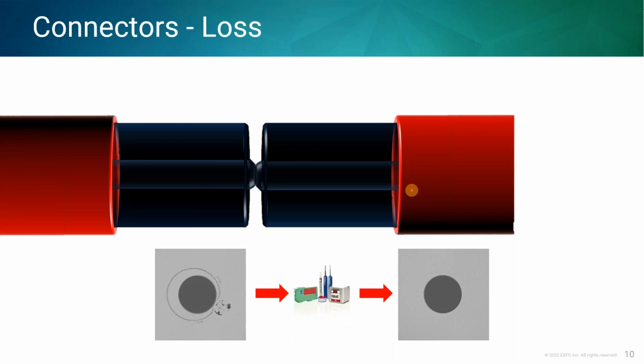I'm a big fan of the hybrid method. Hybrid method being using some sort of a dry tissue, whatever kind of dry tissue you have from whatever vendor, and then some sort of cleaning supply. So these are the two big things that I look at. When I'm cleaning, I essentially just wet a small portion of the dry tissue, start my connector in the wet and pull into the dry. I don't expose it to the atmosphere while it's wet, and I don't oversaturate it with too much solution. Those cause problems in themselves.